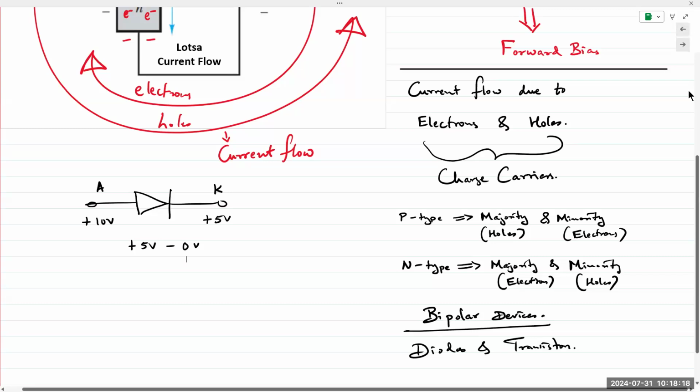A hole is basically the absence of an electron. We are talking about the atomic structure in a material, and when an electron moves from the valence band to the conduction band, meaning it is now available to conduct electricity, it leaves behind an empty spot in its place. That empty spot results in a positively charged ion, and we name that empty spot a hole. For purposes of analysis, we treat it as a particle that is exactly the same as an electron, but has an opposite charge.